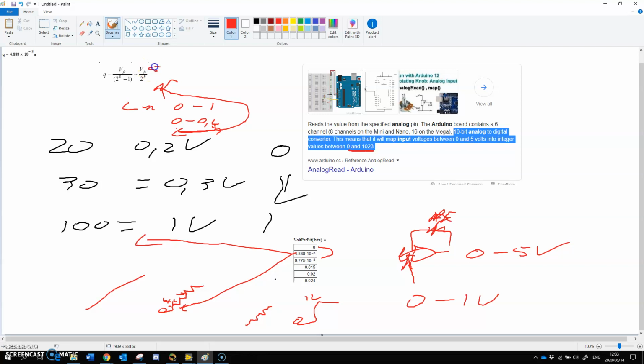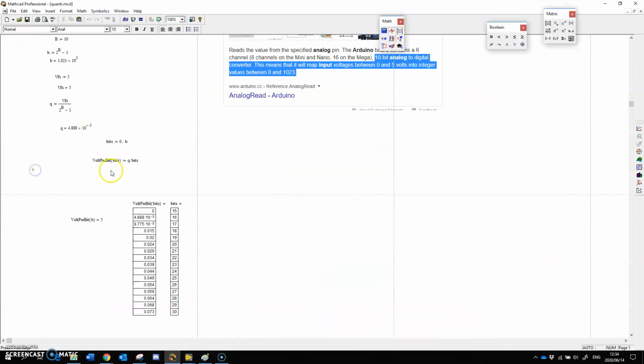Remember that this is still 5 volt, and we still have 10 bits. So you have to see what is your step size and up until how many bits you have just to go from 0 to 0.4. So you have to manipulate your mathematics a bit to see what your resolution is. Step size is still this, so we can theoretically say 0.4 divide by that, and we would know what your step size is. So back to the maths.